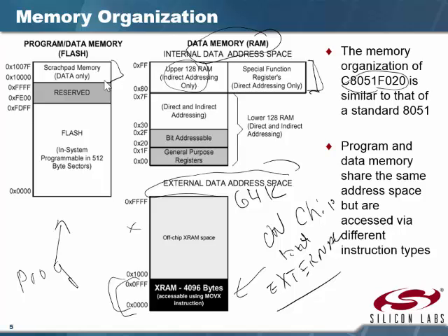Again, this shows that we have this off-chip RAM space. The chip we've got, we can address that, but it takes up so many of the pins that you would never use the chip we're using with external memory. It's only got 16 pins. You need 8 pins just for the data bus. You lose VCC and ground, so 2 of your 16 pins are gone, now you're down to 14. Take the 8 for the data bus, now you're down to 6. You take 3 more for the control lines, and now you're down to 3 pins left for any kind of control applications.